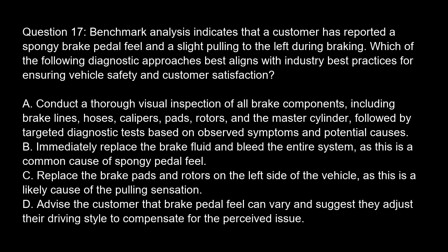Option B. Immediately replace the brake fluid and bleed the entire system, as this is a common cause of spongy pedal feel. Option C. Replace the brake pads and rotors on the left side of the vehicle, as this is a likely cause of the pulling sensation. Option D. Advise the customer that brake pedal feel can vary and suggest they adjust their driving style to compensate for the perceived issue.